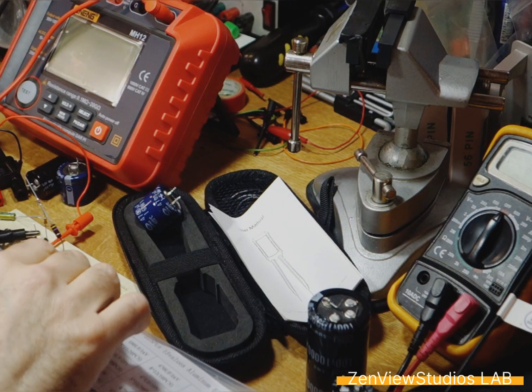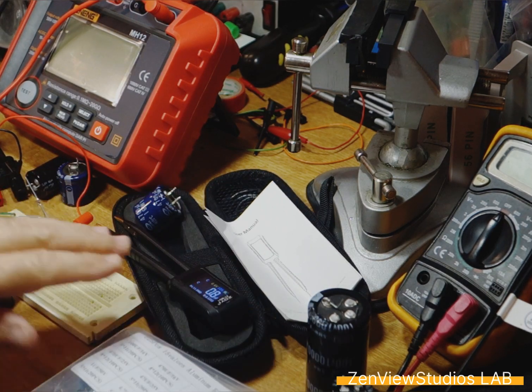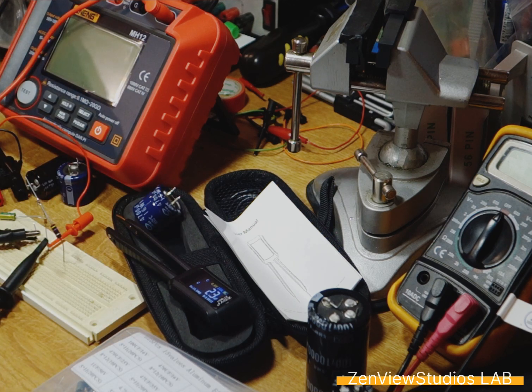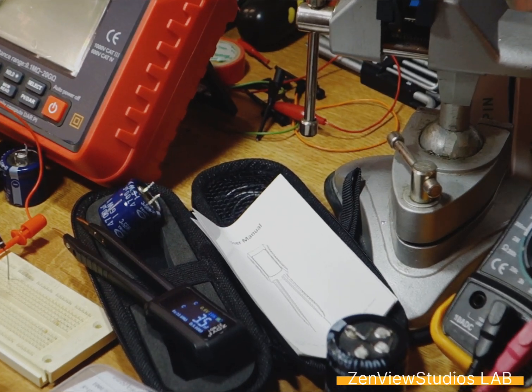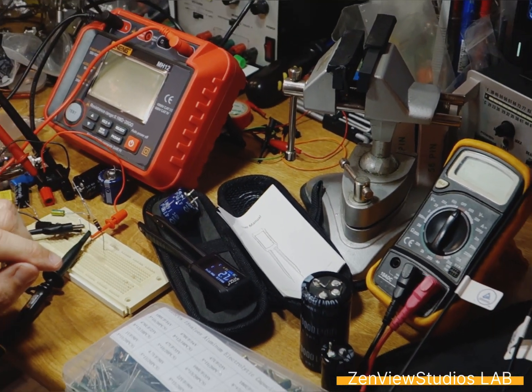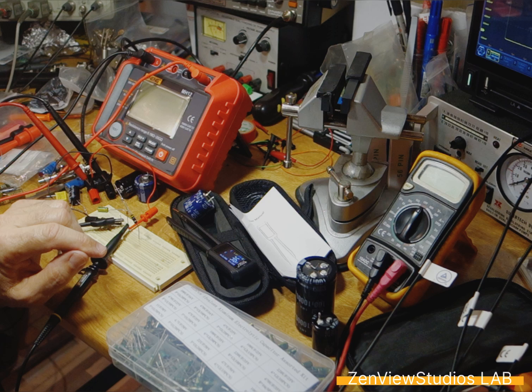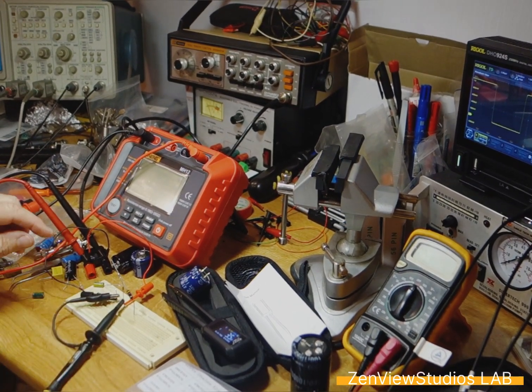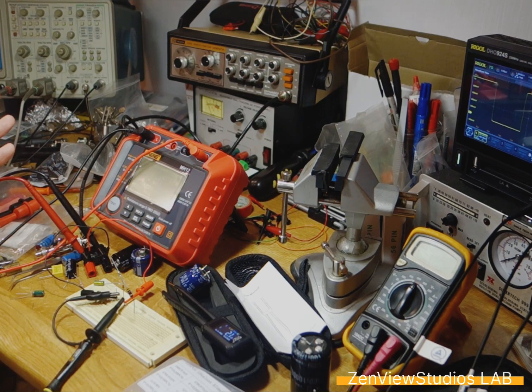So what I measured and showed is that we get an extremely good correlation between this and a 5.5 digit RMS multimeter that measures up to 200K or so with no problem, feeding a 100K signal. So that's really what's also very interesting, is that even though it says 10K, the measurement is close to what you'd get from a 100K measurement with maybe some other LCR meter.